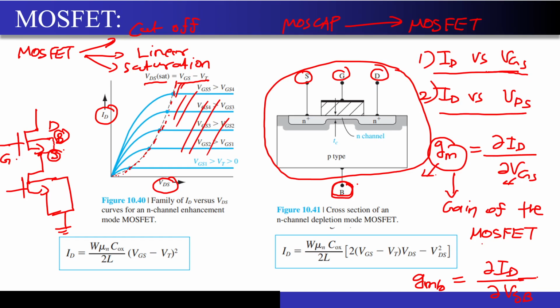Now what happens over here? Now why have I defined this term? Because this GMB helps you to give extra transconductance. So if you have a GM and a GMB, and you need a lot higher GM from the circuit without increasing its size, see this GM that you are seeing over here,